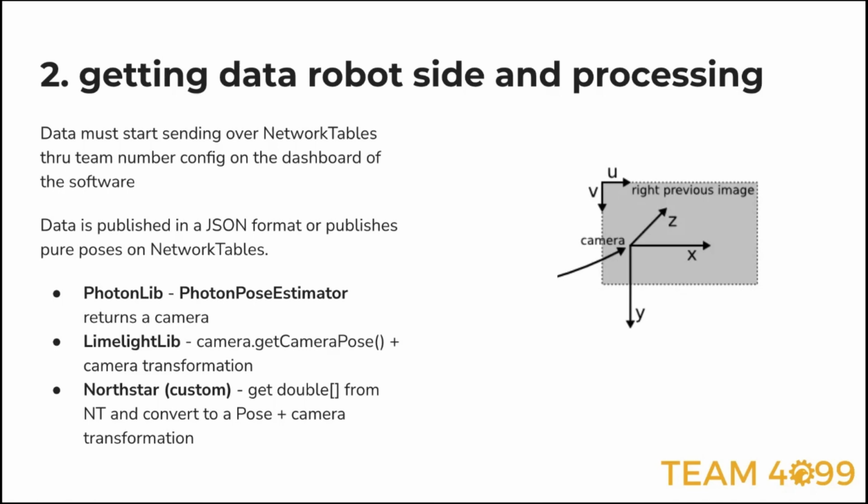So on PhotonVision, what you have to do is you just go to the camera calibration page, and then all you do is take like 16 different photos of something called a ChArUco board, and that'll calibrate your camera. And the reason this is different is just because the distortion within the lenses of each camera will be different, because the glasses will be made slightly differently each time. There'll be imperfections within the lens. All that sort of stuff will make sure there's different calibration constants.